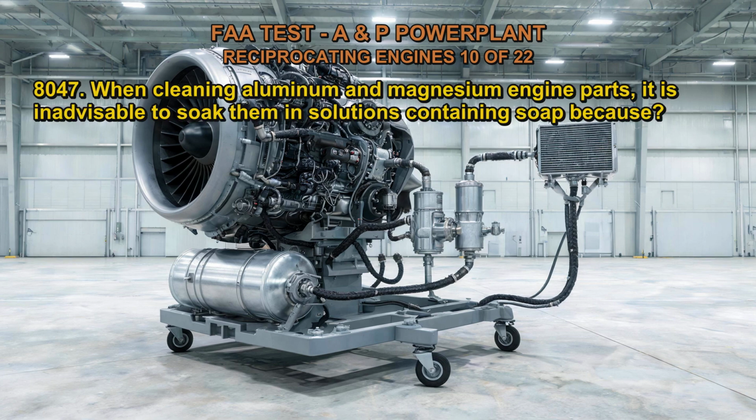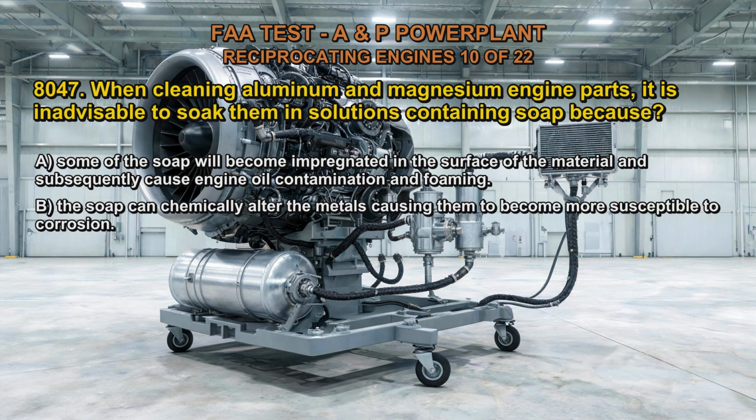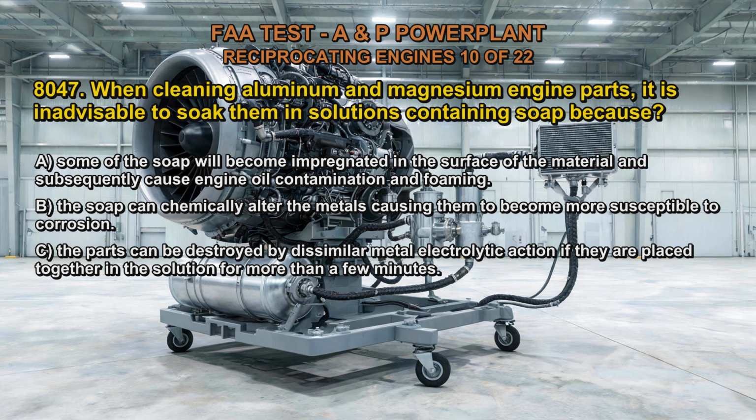8047. When cleaning aluminum and magnesium engine parts, it is inadvisable to soak them in solutions containing soap because A. Some of the soap will become impregnated in the surface of the material and subsequently cause engine oil contamination and foaming. B. The soap can chemically alter the metals, causing them to become more susceptible to corrosion. C. The parts can be destroyed by dissimilar metal electrolytic action if they are placed together in the solution for more than a few minutes.